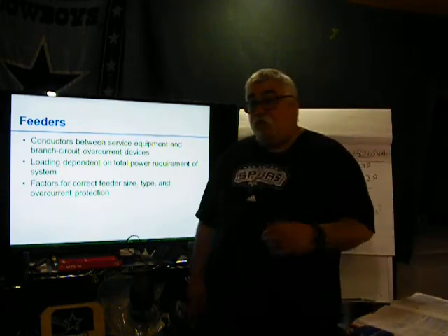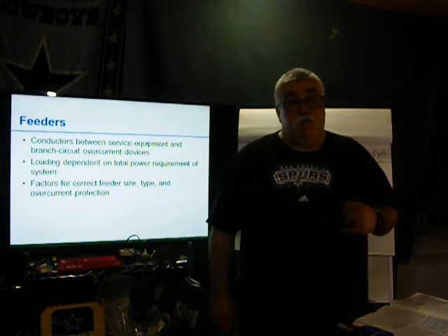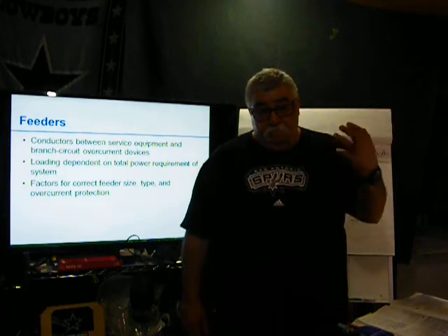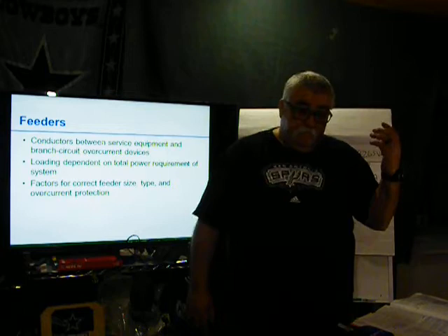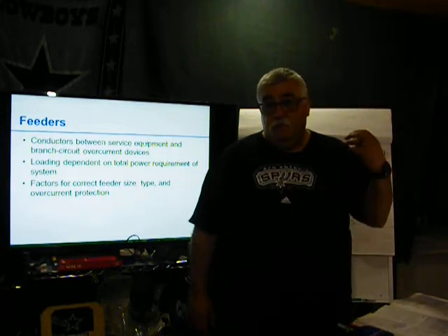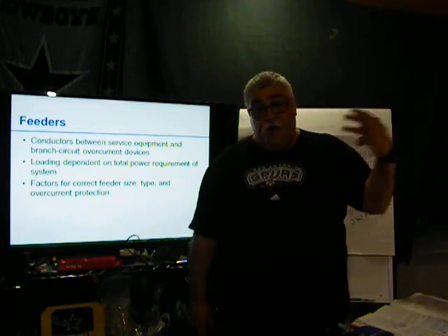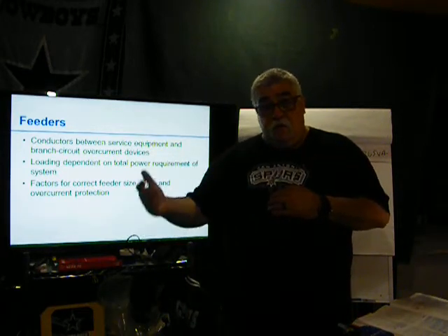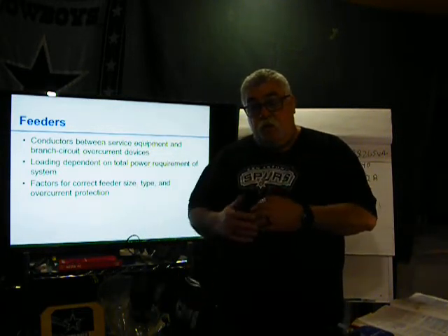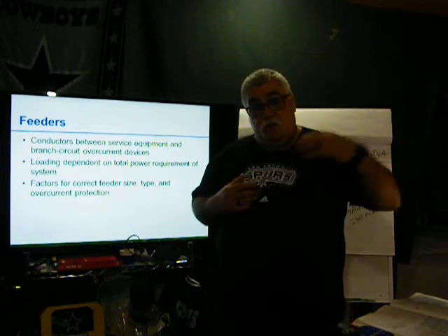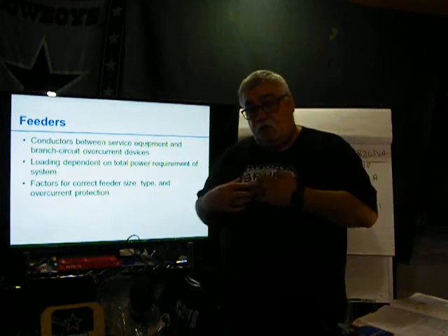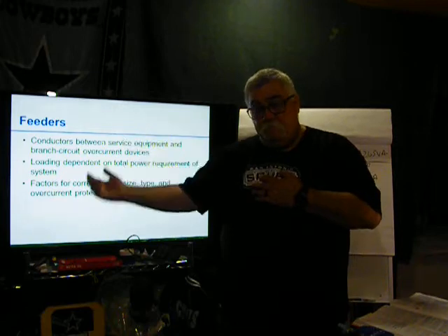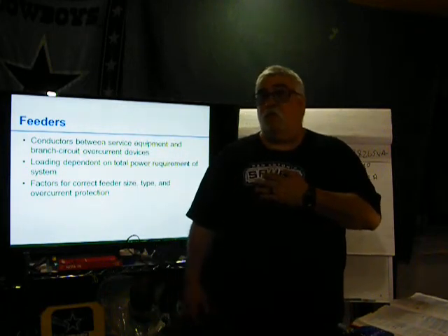Okay, what does it mean by neutral not necessary with a feeder? So let's say we have a 277/480 delta coming in. So all we have is 3 hots going into the building. Then we're setting our own transformer, not the utility transformer, and knocking it down to 120/208 3-phase.